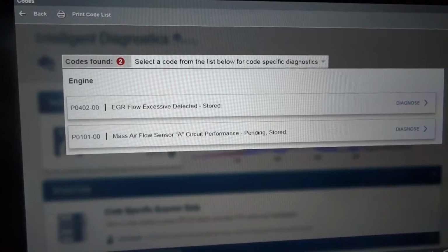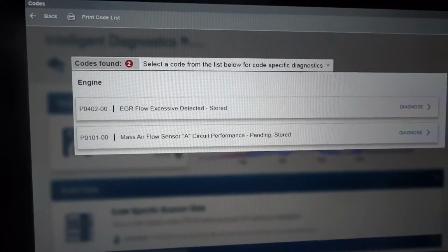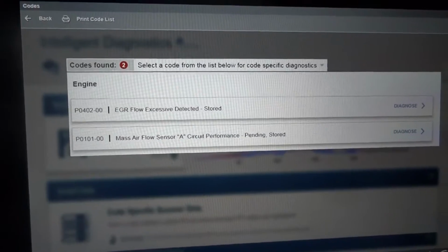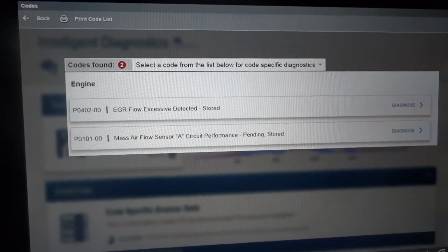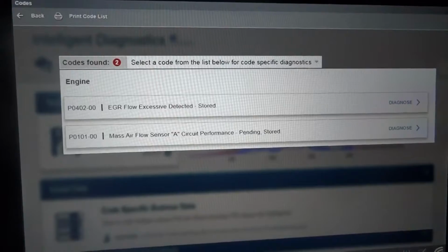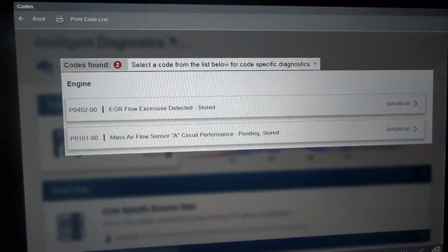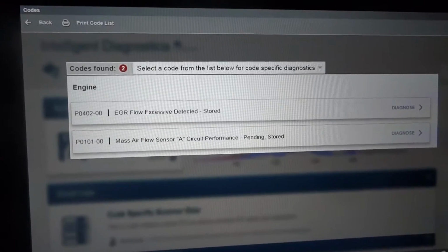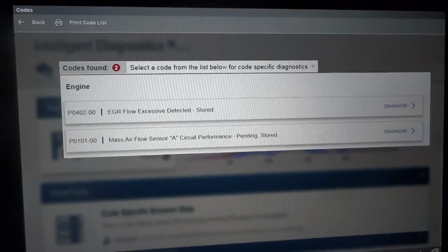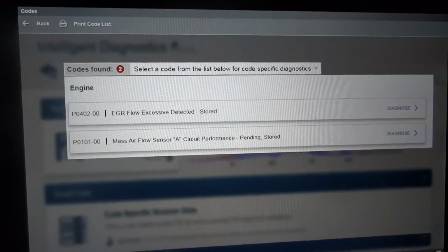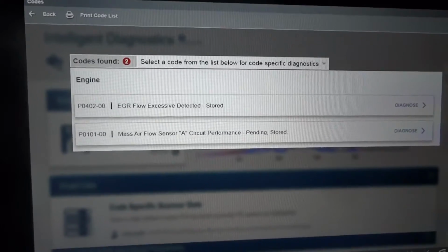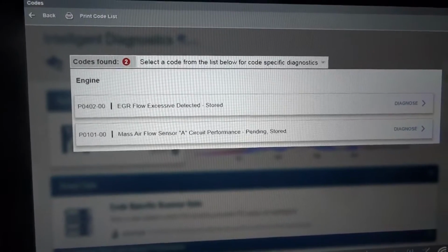Now, how does it work? To cool down the cylinders, the manufacturers reuse the exhaust gases and send them back into the engine to cool the cylinders. So it's basically recycled exhaust gases that go through a cooler, and then they go past the EGR valve that opens and closes, and it goes into the intake manifold and then eventually into the cylinders. And this usually happens around deceleration.